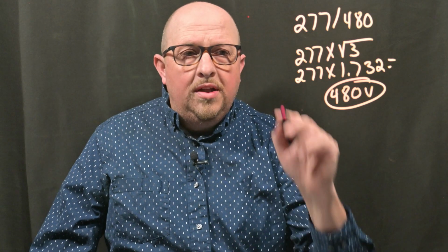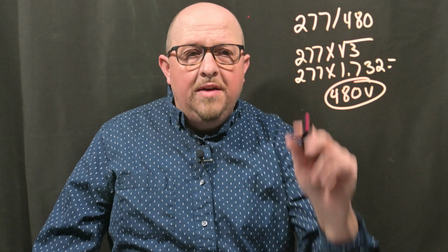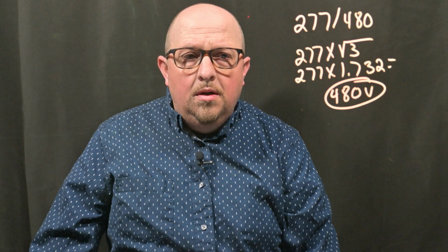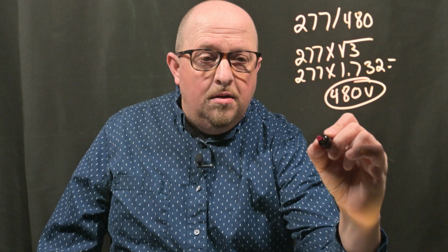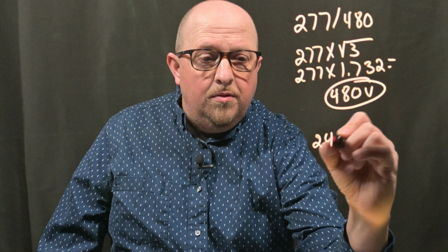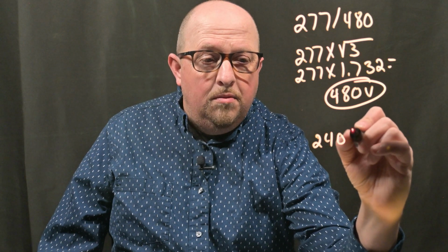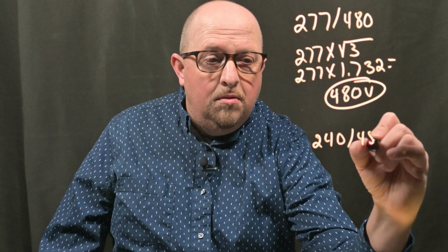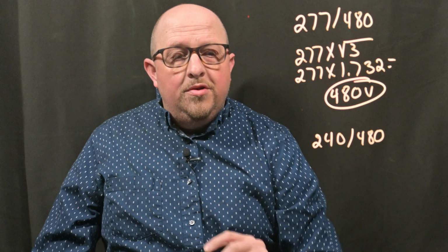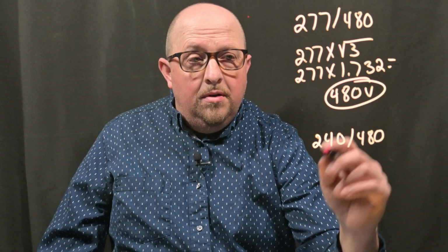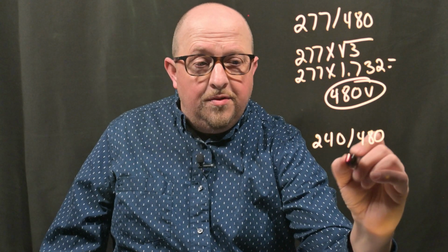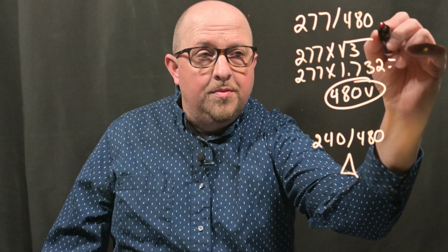Okay, I know that I have a Y transformer. Conversely, if I had a 240/480, these numbers are directly divisible by 2, and I know that I have a delta transformer. And this would be my Y.